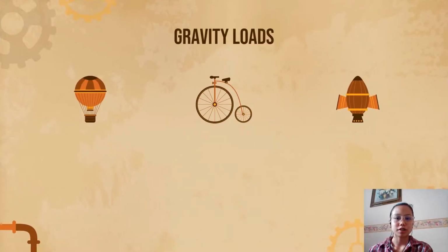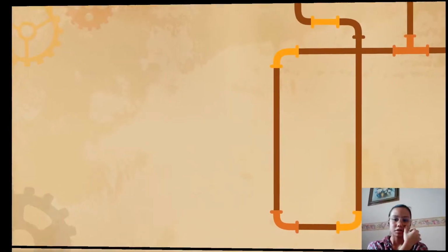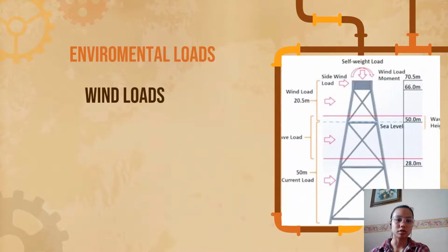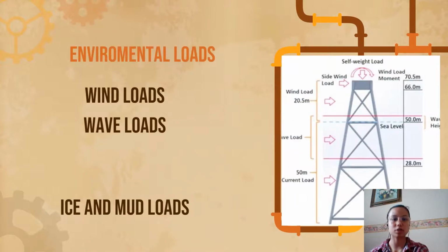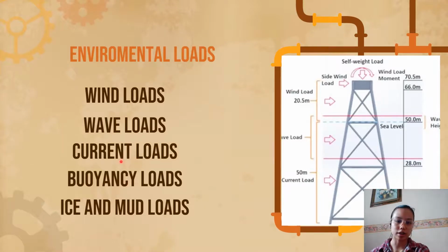So under gravity loads there are structural dead loads, live loads, drilling loads and fluid loads. And then under environmental loads, which is energy load, there are wind loads, ice and mud loads, the wave loads, the buoyancy loads, and the current loads.